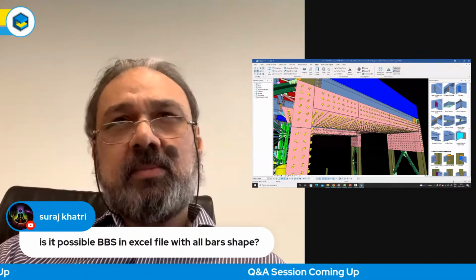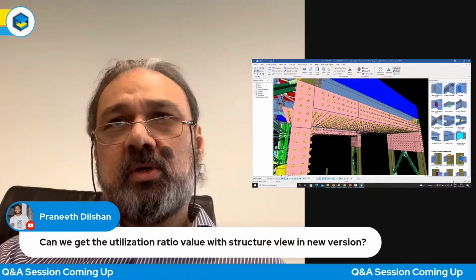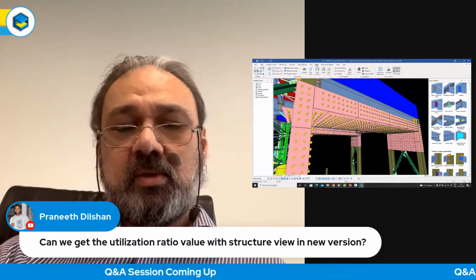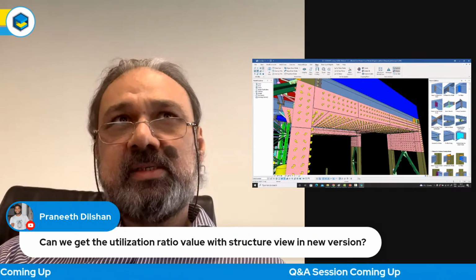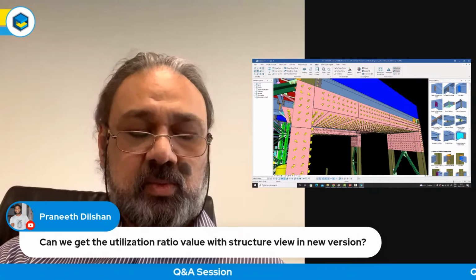There was another question about utilization ratios. That's obviously yes. The answer is yes. We do show utilization ratios with the structure in the new version, and not just in the new version, but it was available in the older versions as well. Whenever you see the design data, you can see the axial bending 2-2, bending 3-3 components of the utilization ratio and their totals as well.